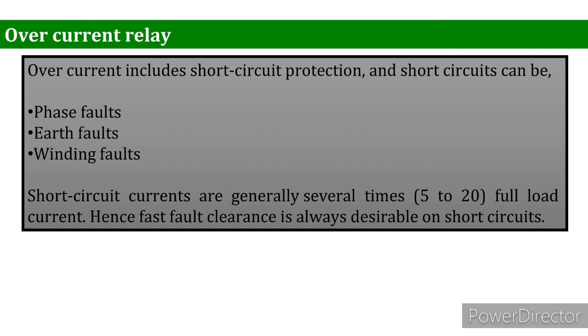For feeder protection, there would be more than one overcurrent relay to protect different sections of the feeder. These overcurrent relays need to coordinate with each other such that the relay nearest the fault operates first. Using time, current, and a combination of both time and current are three ways to discriminate adjacent overcurrent relays, as we mentioned earlier.